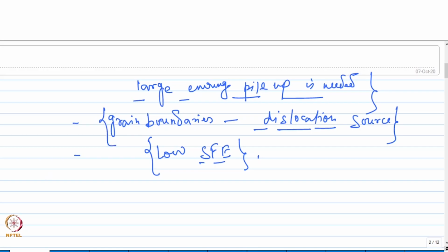So considering this, the theories which were later proposed did not really focus on the stress which is developed by dislocation pile-up. Rather, those theories consider the dislocation density and the effect of grain size on the same.